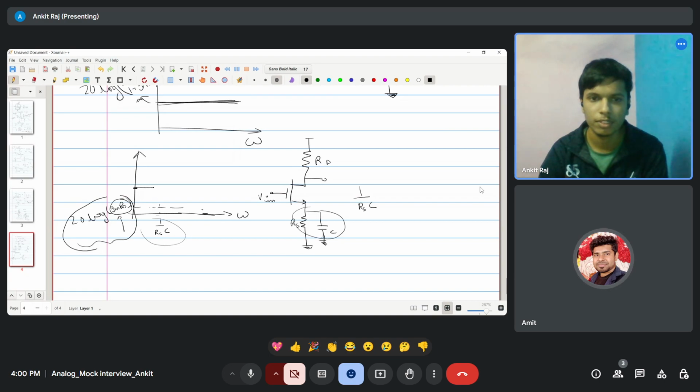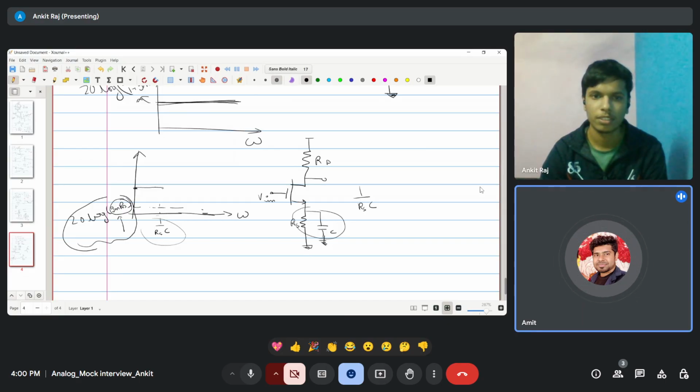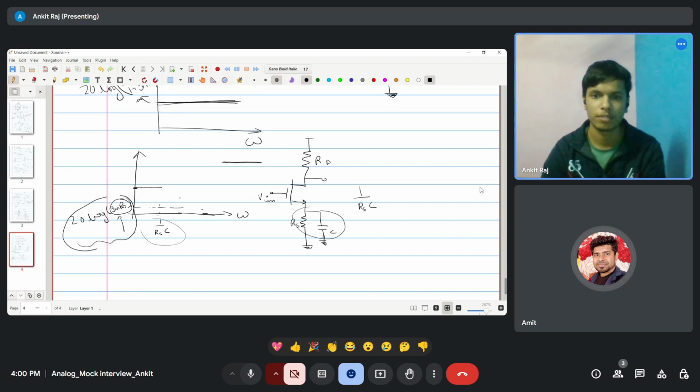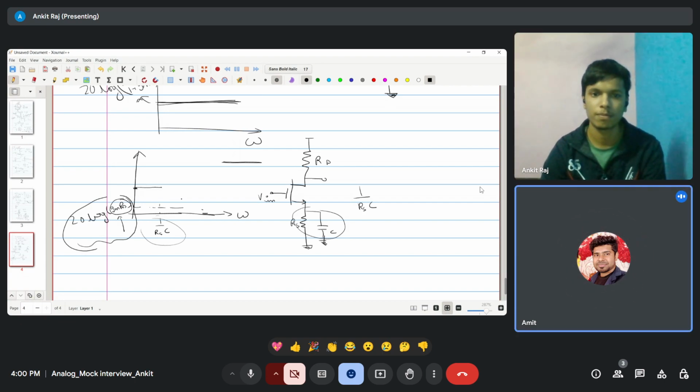Up to some value, and make a higher trajectory at omega equals infinity. We don't know what is happening in between. Just make a higher line. Now we are assuming the Bode plot. It can be a slope of minus 20 dB per decade, plus 20 dB per decade, or 0 dB per decade. If the gain is higher at omega equals infinity, the slope must be plus 20 dB per decade. Mark it as plus 20 dB per decade.